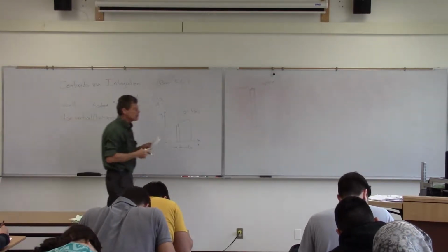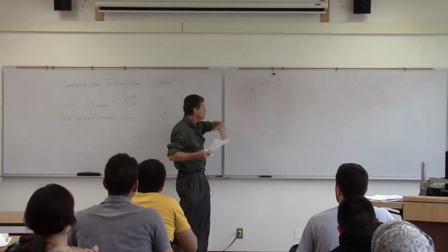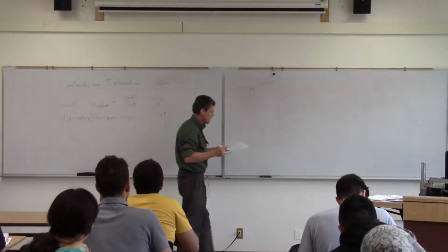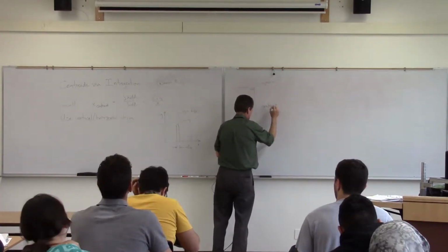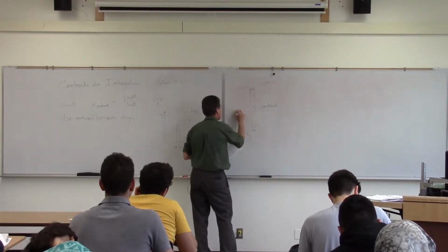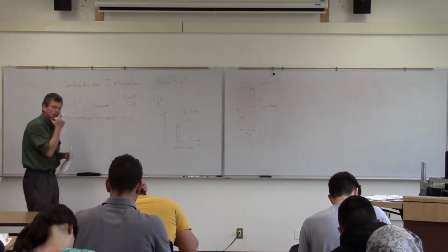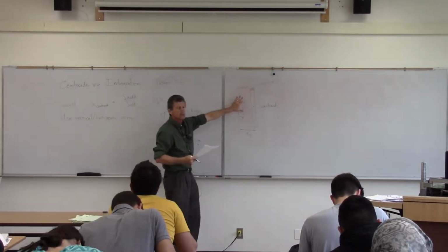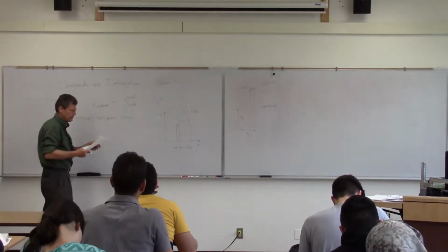And as we make this strip smaller and smaller, what does this look like? Rectangle, right. Do we know where the centroid of a rectangle is? Yeah, right there. So basically, we're going to be able to create first moments of area using this strip. We're going to be able to use integration by recognizing the fact that our strips are really nothing more than rectangles, whether they're vertical in this particular case or horizontal.